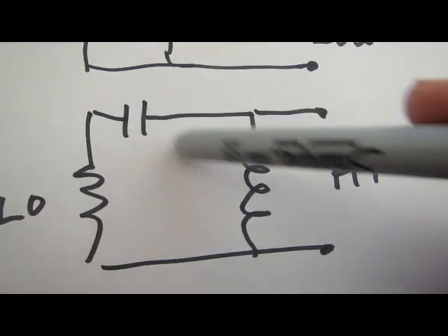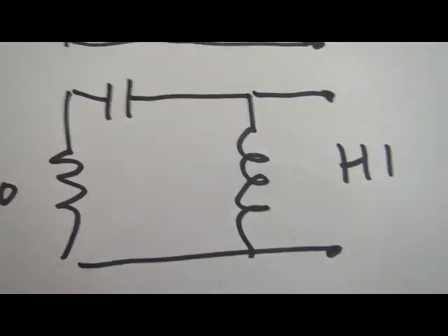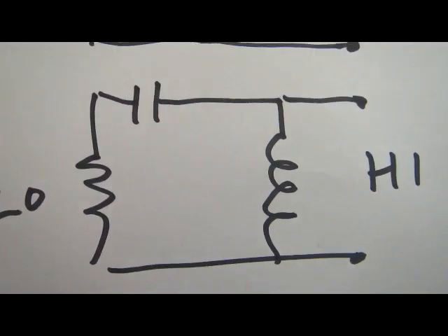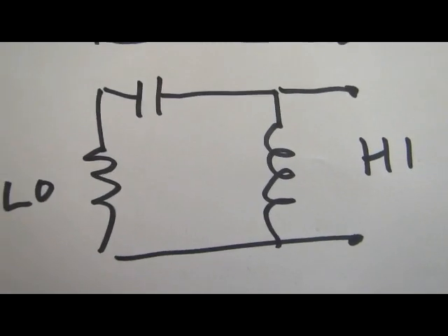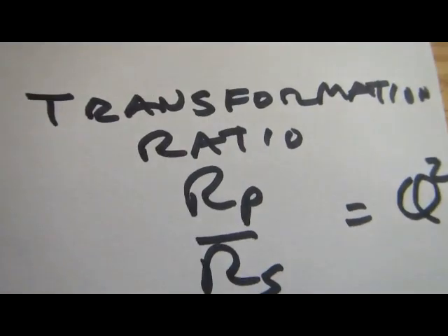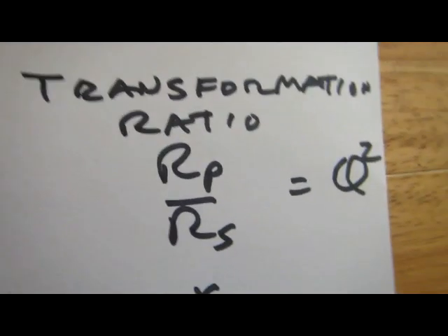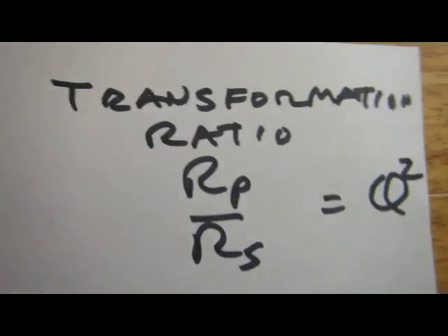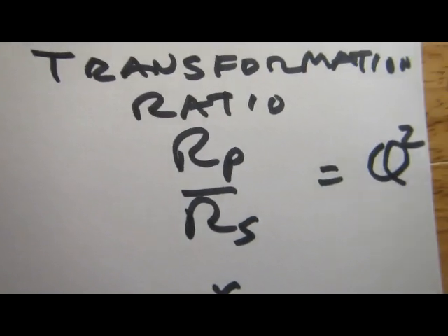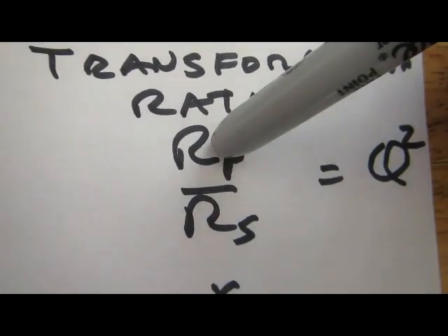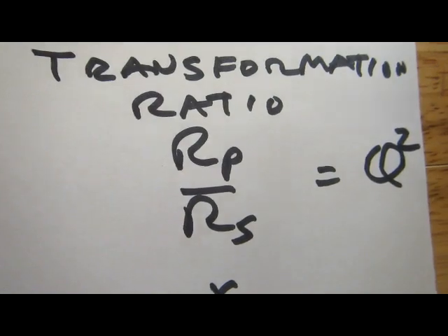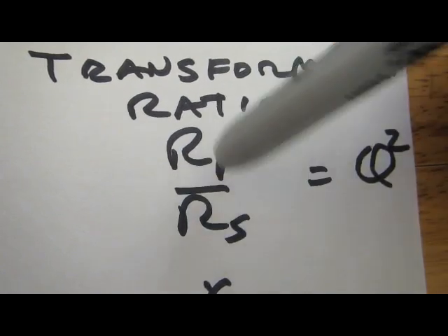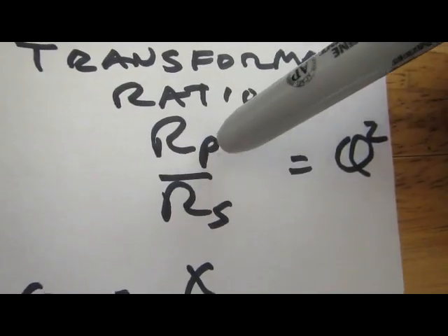You can always reverse L and C, it doesn't matter. It's more to do with how much capacitor swing you have available, things like that, or how much harmonic rejection you want. So that's the L network. Most of these L matching circuits you can do approximately in your head. Usually it's an easy matter, to get it approximately right anyway. So the first thing is just get the transformation ratio. Only look at the resistances. Don't worry about any reactance in the load or anything. So the ratio of the resistances gives you a transformation ratio. Make the ratio greater than 1.